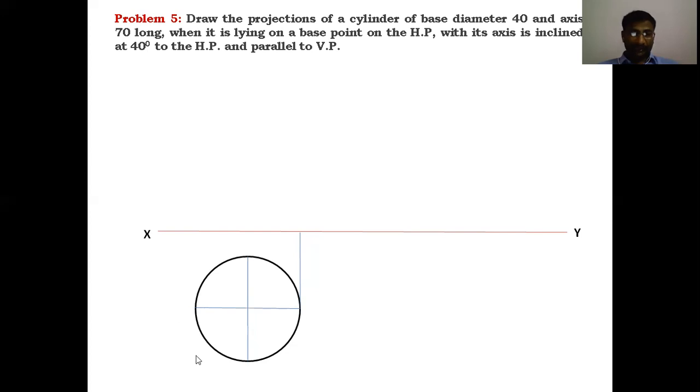After getting this circle, divide this circle into a number of equal parts like this. I divided the circle into 8 equal parts. How to divide this circle into 8 equal parts? This is 45 degrees. For every 45 degrees, you have to draw the lines within the circle. Those lines must be thin, and only the circle is the thick line.